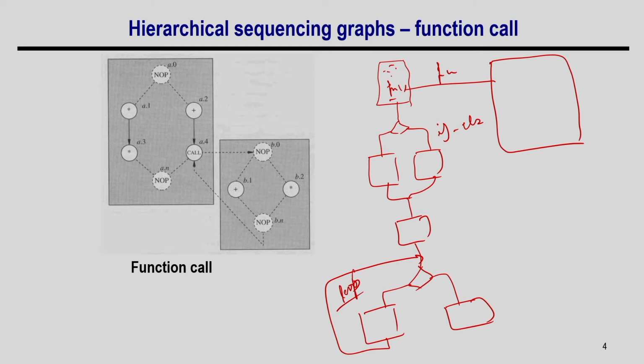So, we have discussed that if we have a straight line of code, there is no control flow: there is no if else, no function call, no loops, just a series of codes written there. If you take only one basic block, then we can solve this allocation binding problem efficiently using the left edge algorithm, because the complete graph will become an interval graph.